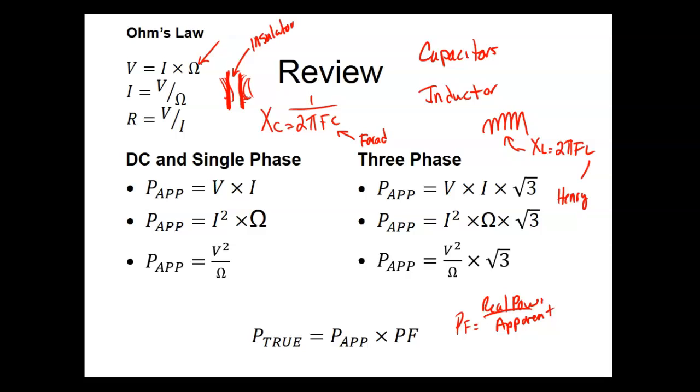And we can compensate for this. We have dynamic power factor corrections where the ultimate goal is to get what we call a power factor of 1. That means the work that you're paying for is the work that you're getting. Well, you can get close. Out of U.S. Steel, they use synchronous motors. So the power grid is predominantly inductive because all your transformers are inductors, all your motors are inductors. Well, what we can do is we can add capacitors and it'll bring it back into phase.